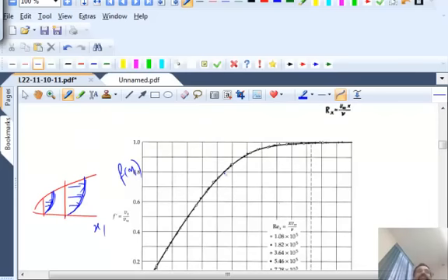How would you generate such a graph? Question, yeah. Is that still true even after it goes beyond? No, it's valid only in the laminar regime, because the Blasius solution and Prandtl boundary layer equations are all valid only in the laminar regime. So this is valid only when Reynolds number is less than 2 times 10 to the 5.